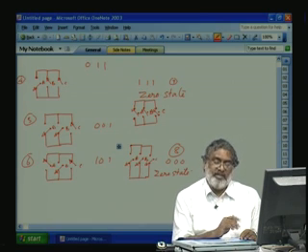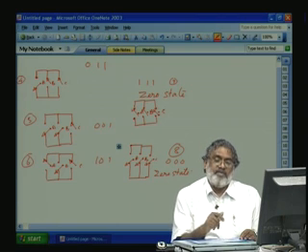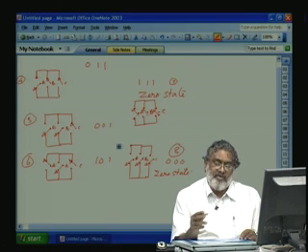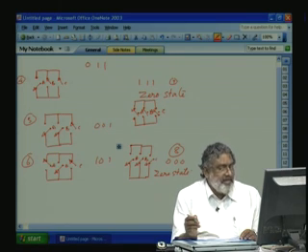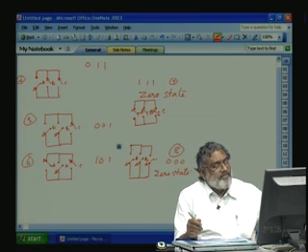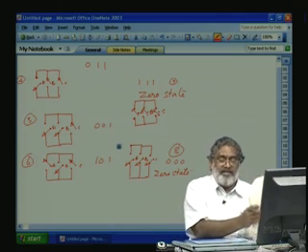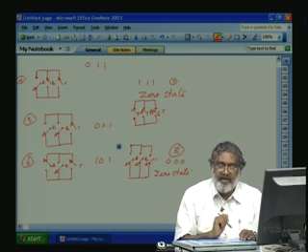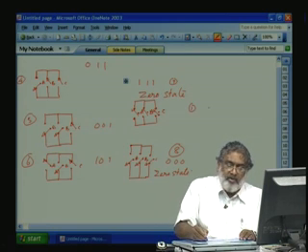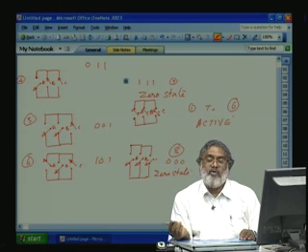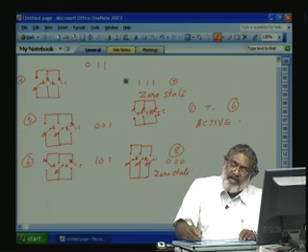So, how do you use these states such that the average variation in phase is sinusoidal, or the average voltage space vector's tip will trace a circle? Now let us see, in a sequence starting from 1, 2, 3, 4, 5, 6, these are the active vectors. The states 1 to 6 are called active states. That means these can only produce a non-zero output voltage space vector.